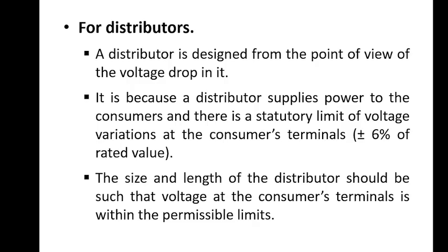Therefore, it is essential that the design of the distributor, particularly its size and length, ensures that voltage drop along the line does not cause the customer voltage to fall outside these permissible limits. So proper selection of conductor size as well as controlling the length of the distributor helps maintain stable voltage levels and ensures reliable and high quality power delivery to end users.